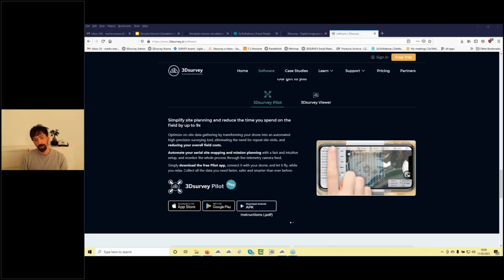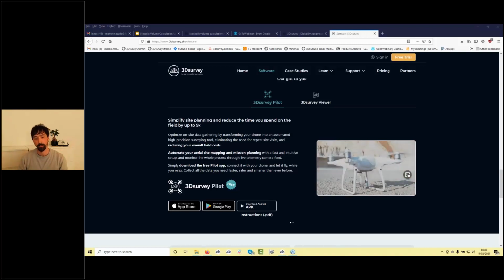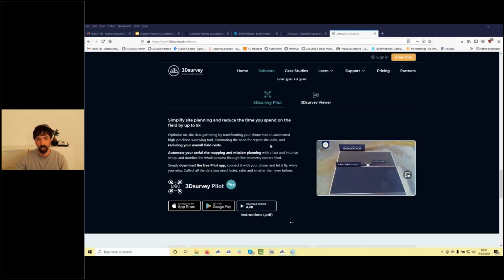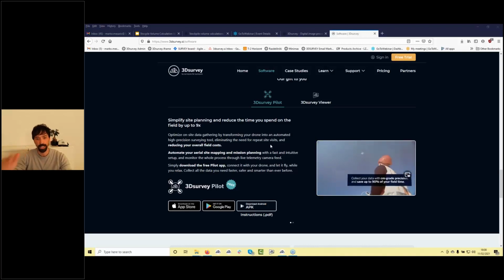So even when we use just a single GCP point in addition, we improve this displacement. Horizontal position is always perfect, but for height we still advise using at least 1 to 4 ground control points per project. So I would advise the RTK if you have a lot of projects. If you're doing this once per month or once per 2 months, then take the Phantom 4 Pro.